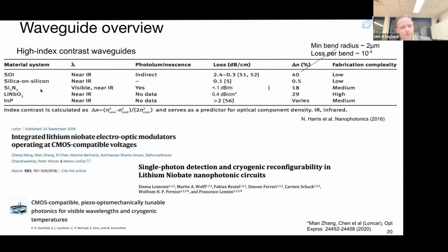In silicon nitride, for example, you can get very, very low waveguide losses, I think substantially even below this number of 0.1 dB per meter, but that's typically by deconfining the mode. That means the devices would take much more footprint. But for some things, if you want to do a buffer, for example, or a really good filter, that's fine.